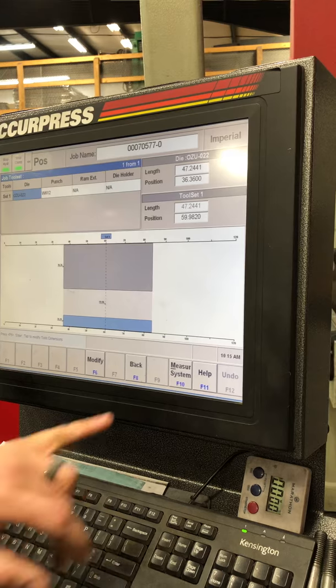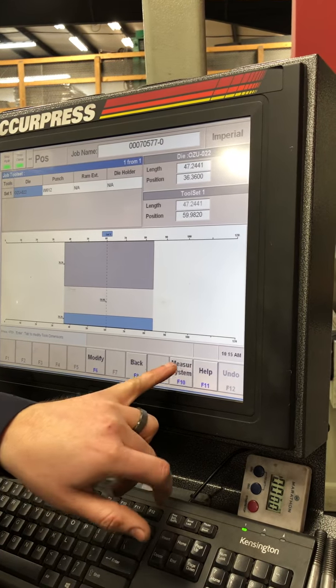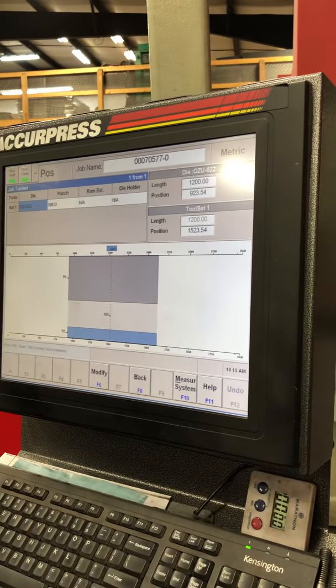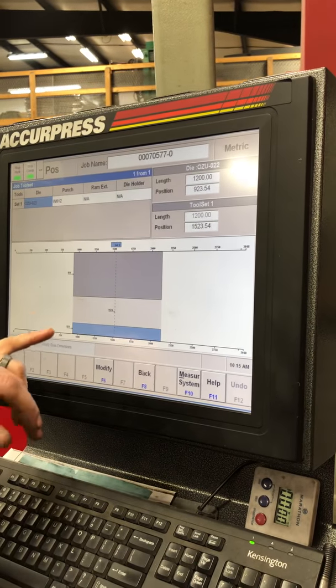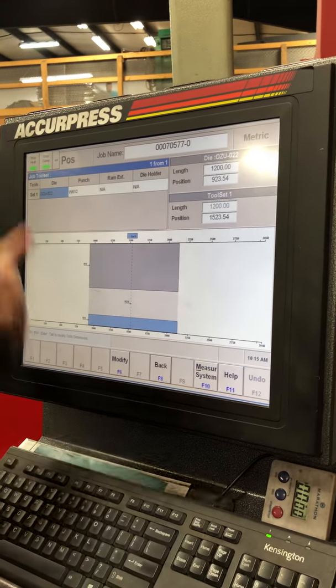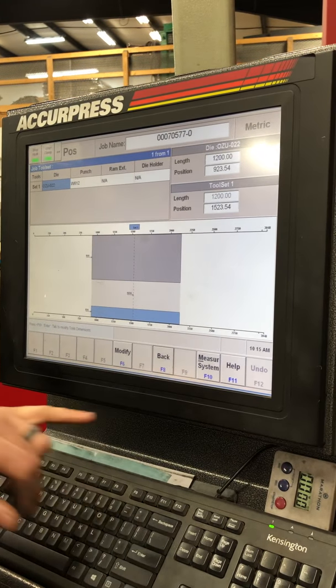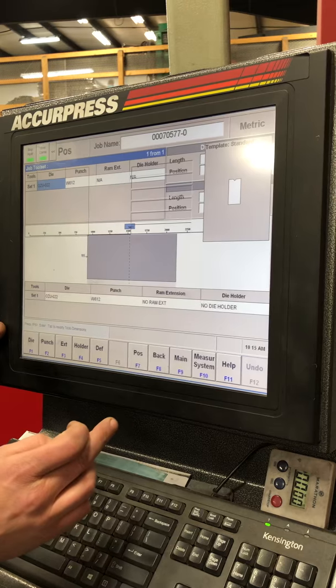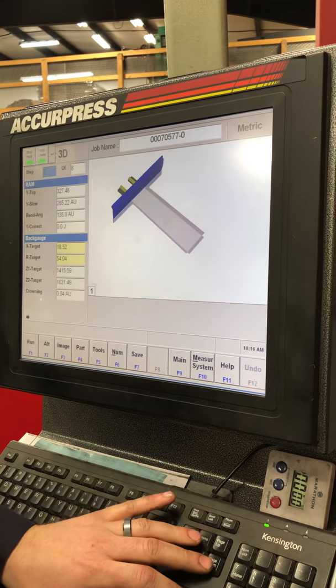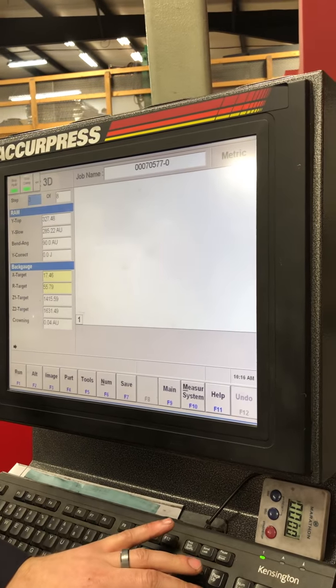All of our tools are in millimeters, so we've got this button here which allows us to convert our inches to millimeters, because we run everything on inches, right? And it's going to tell them what their tool links are, where to put them. Once they get those in there, we'll clamp our tools into position. And then they're going to come back into their program, and then we can paste down to the program, and it's going to show you how to put the part in.